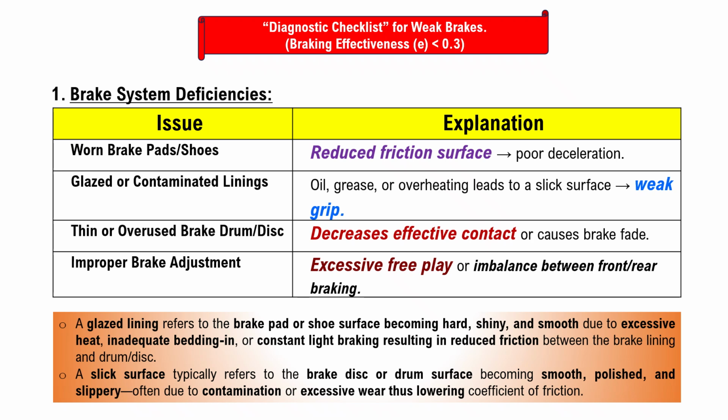Thin or overused brake drum or brake disc. It also decreases effective contact or causes brake fade. Improper brake adjustment, that is, excessive free play or imbalance between front and rear braking.